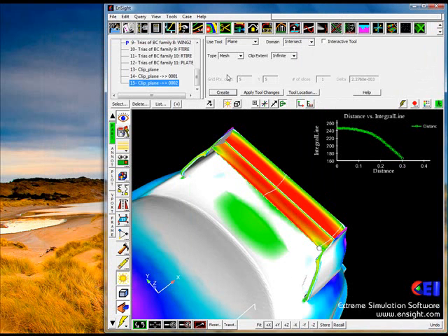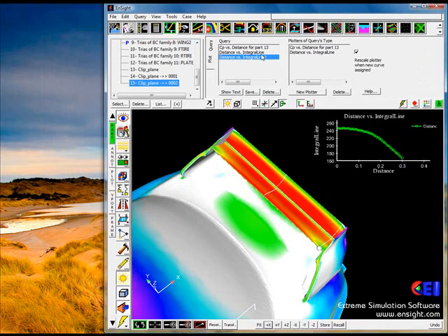Okay, that's done across the span. Now we go to our query again, and we can see we have another one here. We can add this to this particular graph by saying that we'd like to add it to this one. So now we have two values. We have the flap and the main wing. You can see the flap actually has reduced load at the center line, picks up load, and then decreases out, where the main plane pretty much drops load all the way across the span.